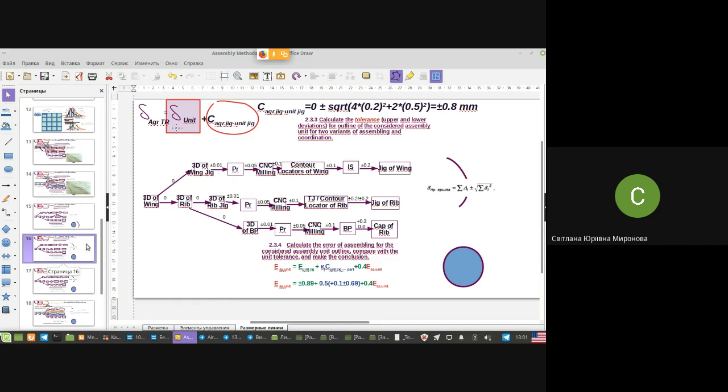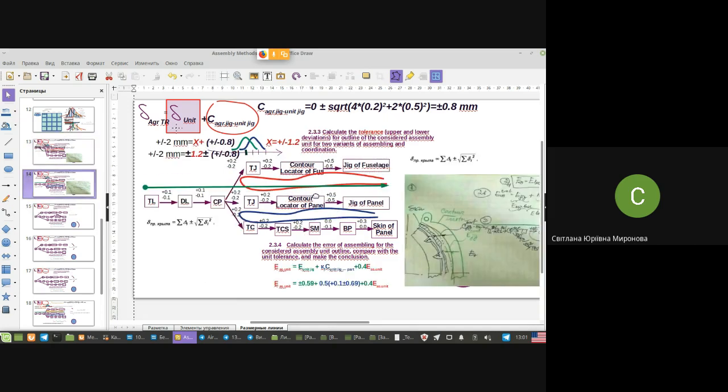Second thing, also an important consideration: it's not compulsory to use even mockups or templates for mounting the jig. Really, maybe I already said it to you, these values that I wrote here, plus minus 0.5, are reduced values in order not to scare students with real values. So when we use templates as a means of mounting, these values will be even greater.